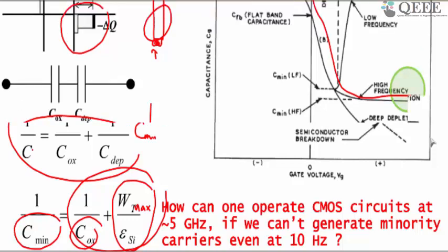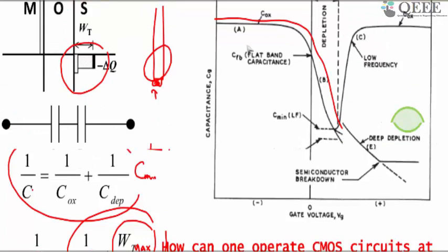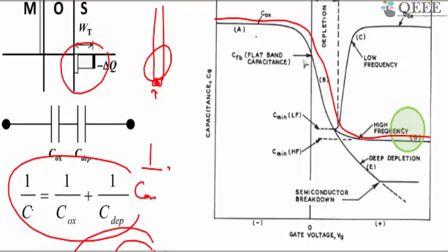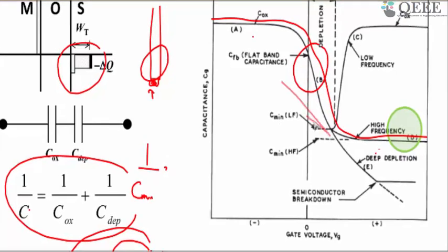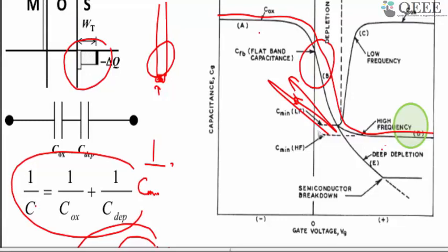So then this poses a dilemma, right? Essentially, you are transitioning through accumulation, depletion and inversion. That's the same condition which happens in a transistor. When the transistor is on, it is full of inversion layer: the surface is inverted and full of electrons. When it is off, it may go back to somewhere here, to depletion. So it has to constantly switch on and back, going back like this.